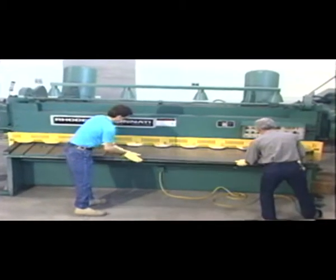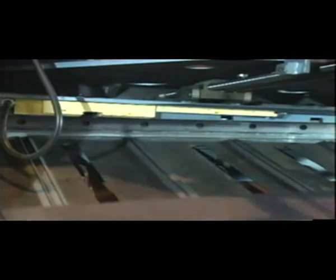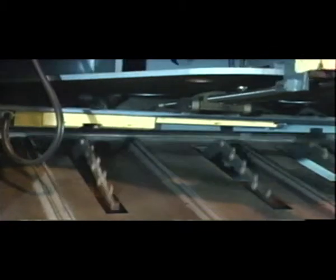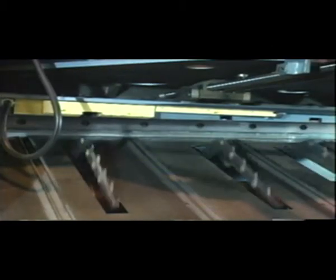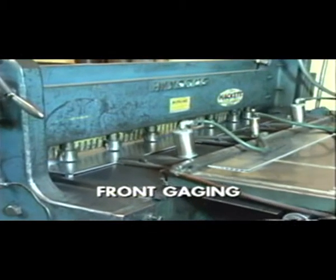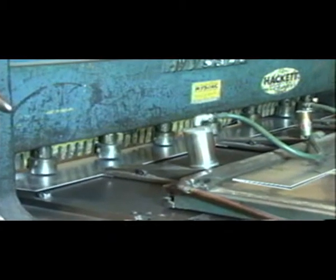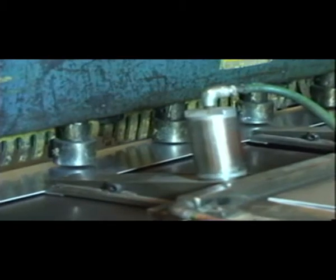To eliminate this problem, a sheet support system can be added to the back of a shear. Generally, a sheet support holds the workpiece in a horizontal plane until it is cut. The support then pivots down, permitting the workpiece to drop. In front gauging, the sheet is located with respect to the cutting edge by means of adjustable stops or gauges located in the table or front support arms.